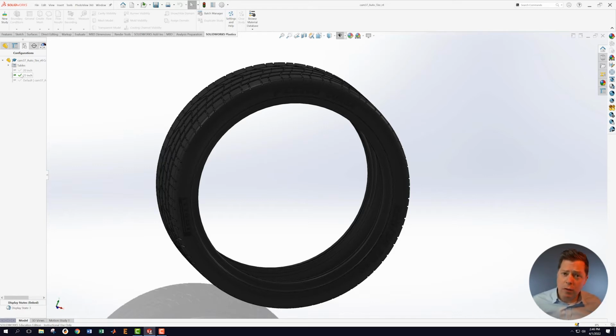I can also see that the goal of the test is for me to make a BMW car rim that will actually adjust its size to the wheel when the wheel configuration is changed. So I need to model the rim. I'm going to need to use master modeling for that to link the two files together. I then need to adjust the appearance of the rim and add the BMW logo. I need to demonstrate that the master modeling is working by seeing that it adjusts. I need to run an interference analysis, and I need to choose lug bolt clearances.